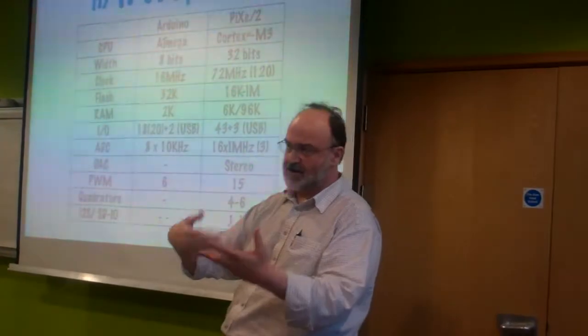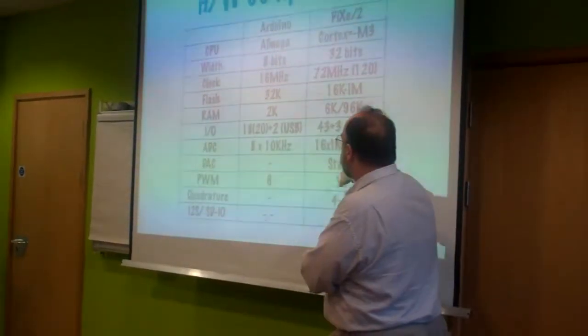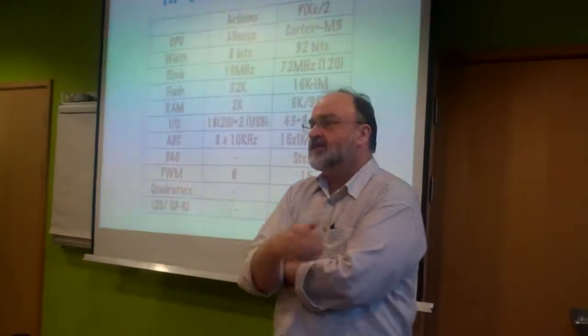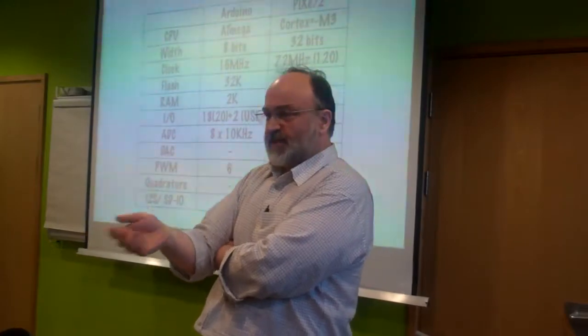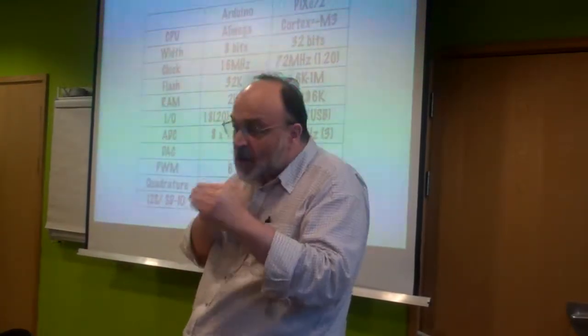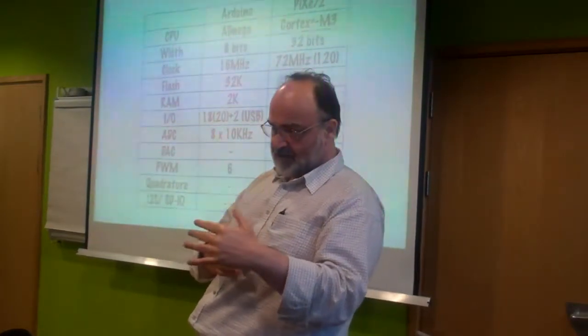And it's got DMA on board, so it can squirrel all of this away and do things. The highest spec chips have got stereo digital to analog. Again, just 12-bit, but by the time you stick them through crappy earbuds and an MP3, we don't know, but we don't think it's very far behind just an ordinary cheap MP3 player.